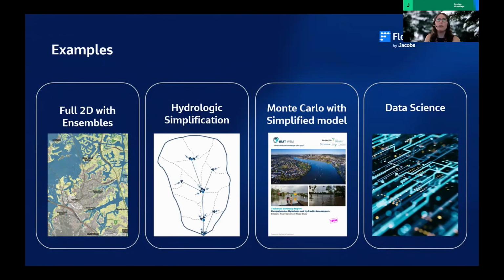And I guess the final current buzzword, using AI. So the use of AI or data science in flood modelling is becoming more accepted. Machine learning-based models can be trained on a detailed hydraulic model to predict a range of flood behavior, again reducing the number of hydraulic simulations in a detailed model. Improved results have been demonstrated by combining this approach with a low-resolution hydraulic model, similar to the previous example, where AI is used to convert low-res results to high-res results, significantly reducing the runtime.